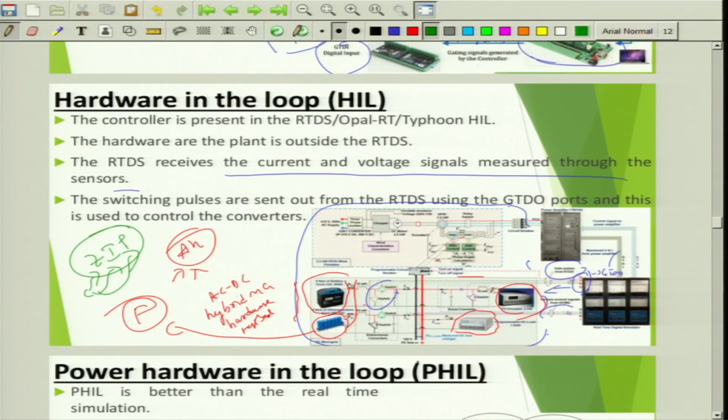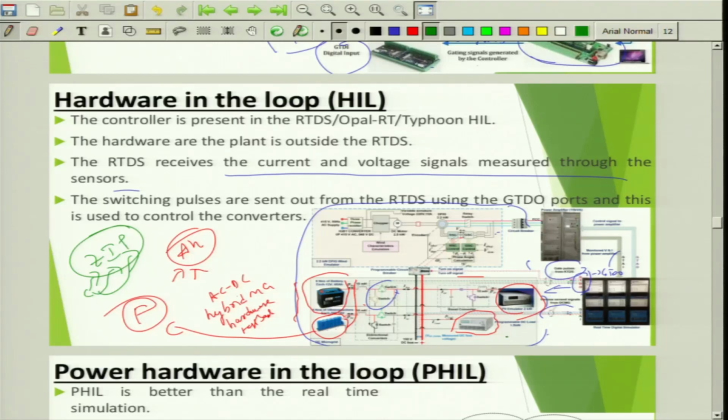Any load that you see in real time may be categorized into one of these types: constant impedance, current and power. Let's say this bulb load. Bulb load is a constant impedance load. The impedance is fixed, so if there is high voltage, there is a corresponding current. Those characteristics can be emulated through this programmable electronic load. You can also program at what time you switch on a specific load, and the change in power, impedance or current can be emulated there. Now all of them put together are connected to a 2-wire DC bus.